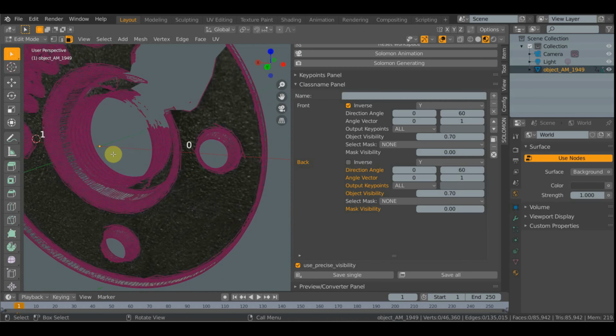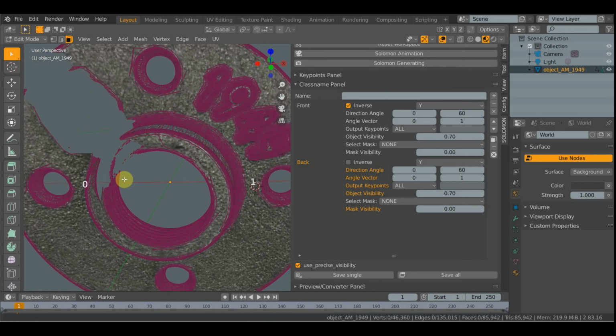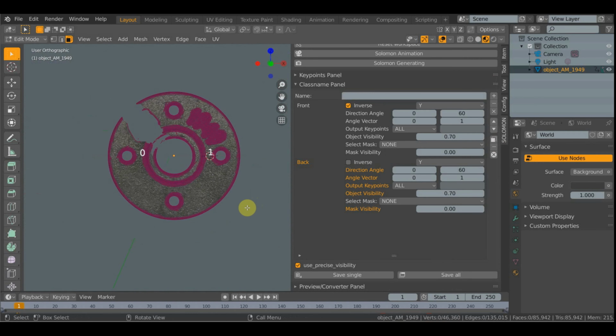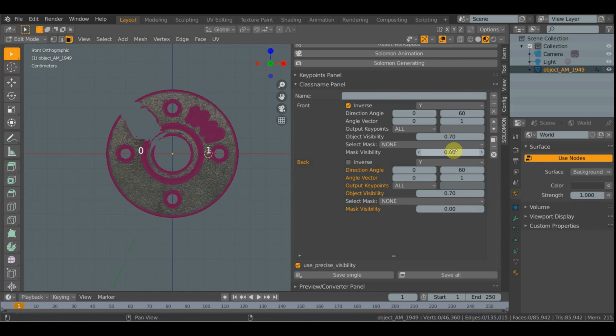With this cropped CAD model, we can give a name to this mask. I suggest you give a name using the name of the class as a root, plus any other extension in order to know the relationship between the new mask and the class. Then, click on the Export the Mask File icon, and immediately the customized annotation has been created. We just need to designate it into the proper class and apply a percentage in mask visibility.